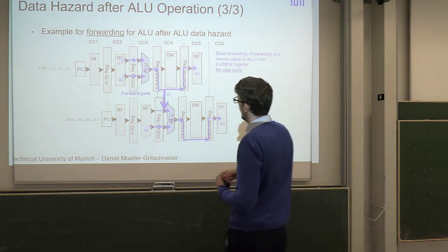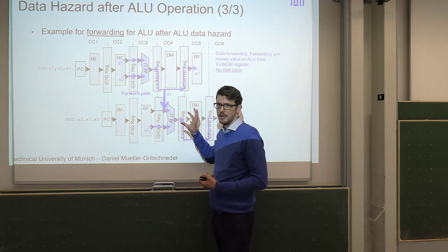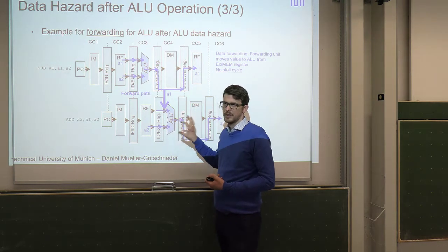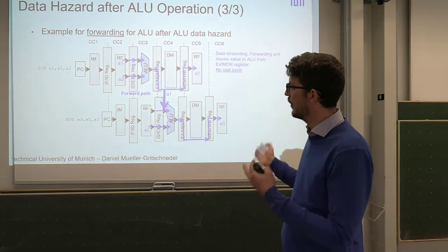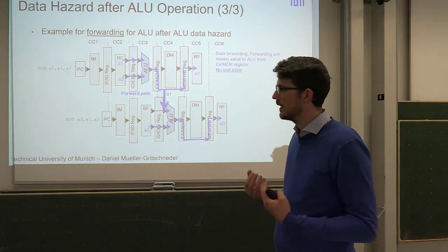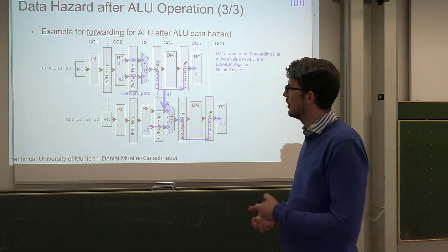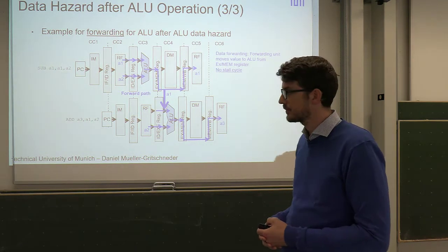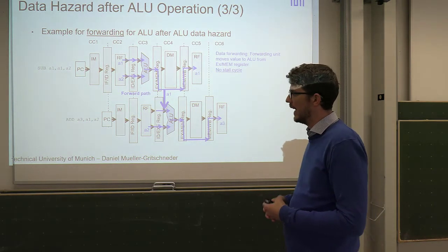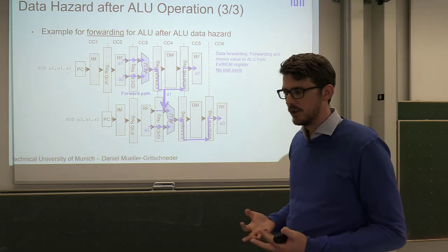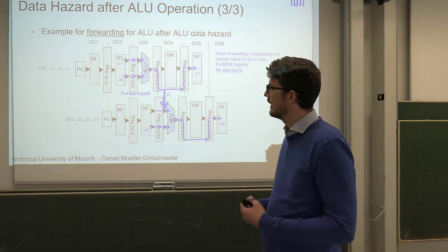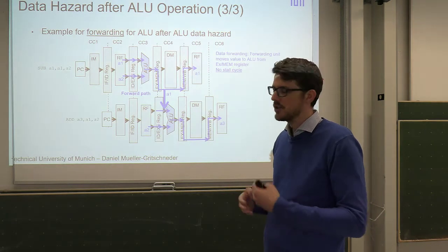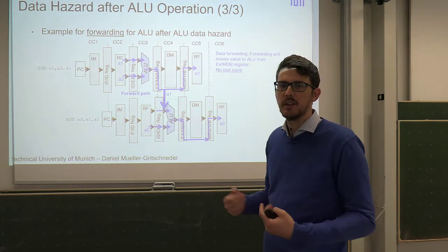So again, most or almost all embedded processors have this forwarding path. Even if they have a 5-stage pipeline, they have this forwarding path, so you don't see any additional delays when you're doing this operation. Another way of dealing with this, if you don't have these forwarding paths, is that the compiler has to make sure it looks for instructions it can put in between which don't have these dependencies, right?